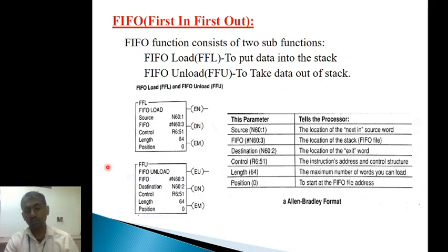One is for FIFO load and another is for FIFO unload. That means in order to put data we use the FIFO load command, and in order to take the data from the stack we have to use FIFO unload. Sometimes it may be represented as F in, and sometimes as F out.